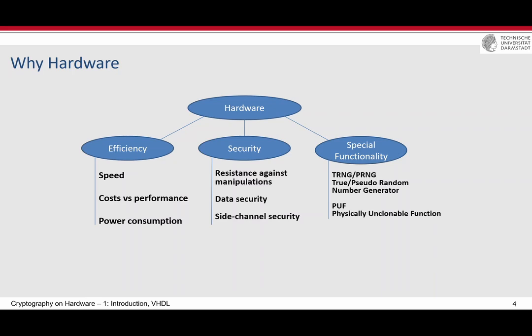It means that some of you are familiar with cryptographic primitives like AES, a standard algorithm for symmetric cryptography. If you implement AES on hardware or software, in a microcontroller or ASIC or FPGA, and you think AES is secure and I implemented it on my device, it's still possible to recover the key which is stored in the device using the power consumption of the device.